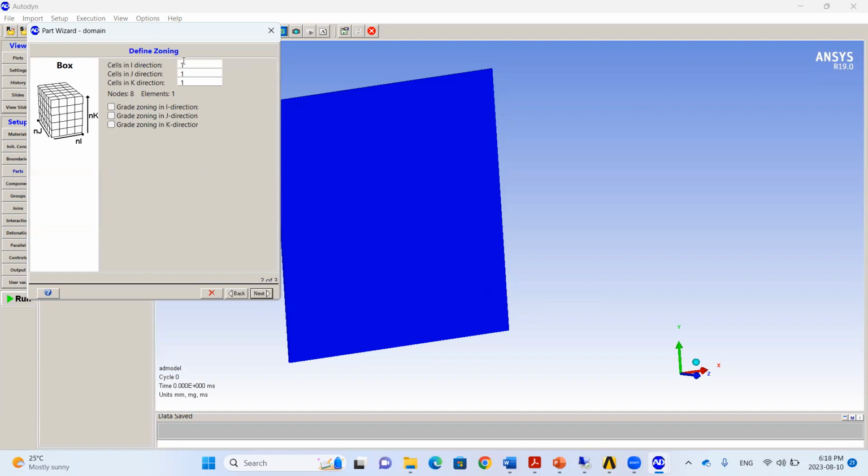So now we're going to divide our cells, which is the meshing. This is very important in large experiments, which need to be more accurate and need sensitivity analysis. So for now, we'll make the maximum element size 1 centimeter. So in the x direction, we will have 120, in the y direction 110, and in the z direction 300. This makes around 4 million elements.